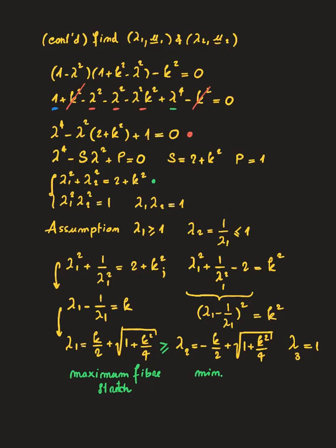Now there remains of course a question, a similar question you find in the problem sheet, but essentially it was the question for which we started. If we have the block in its reference configuration, in which direction are we shearing the block? I'm only drawing one face. In which directions do I find the fibers which are more stretched? Maybe this, maybe this, maybe this, maybe this. So, the question is, what is the direction relative to the mostly stretched direction? Well, for doing that, we have to compute the eigenvectors.